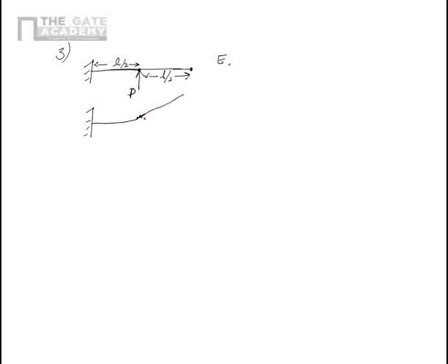So had this beam been free, it would have been like this. It rotates. This is a rotation about the force application point here. So this rotation is equal to theta multiplied by radius. We know that the arc is equal to theta multiplied by radius. So I'll just say rotation arc is equal to theta multiplied by radius, where theta is the slope here. This is theta, and this is the radius, which is equal to L by 2.